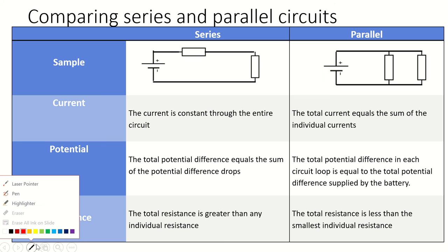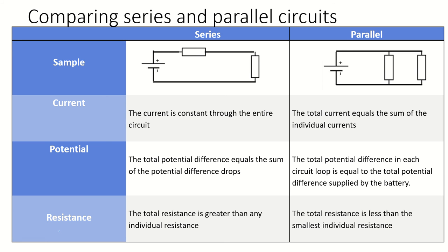So in this video, we're going to be looking at parallel circuits, but before we do, I'm just going to quickly recap series. Components are in series when they are one after another like this, and we know that the current flowing through this series circuit is constant throughout. So the current here is equal to the current here, all equal.